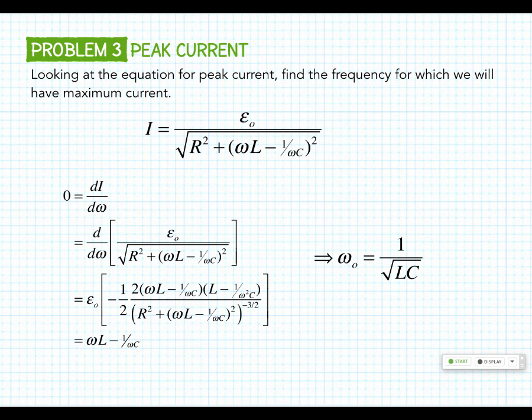All right. So you have to do chain rule. You can see you have to pull this thing up. So you guys have taken calculus allegedly. Anyway, it ends up being relatively simple because you set this equal to 0, so everything in the denominator is useless, and then you just have to worry about the numerator, and the numerator just has 2 terms, and you just set them both equal to 0 and solve, okay? What that gives you is 0 equals this, which gives you omega is equal to 1 over the square root of LC, which is pretty simple, okay?